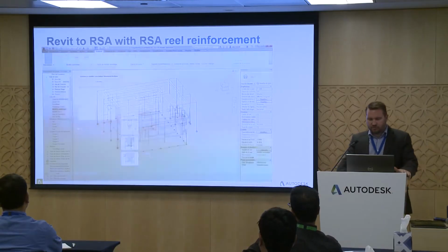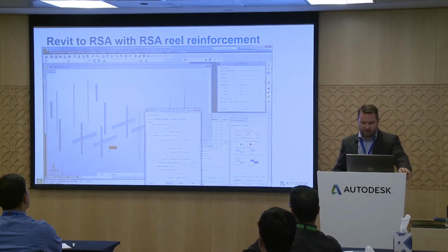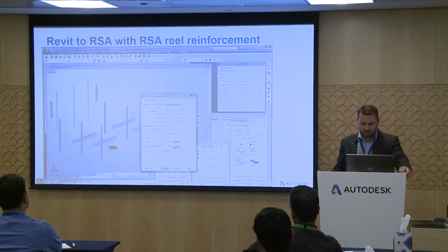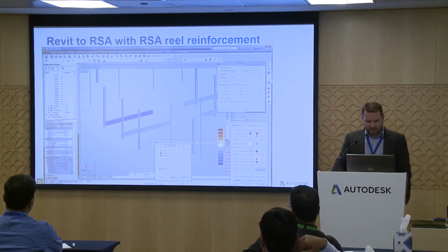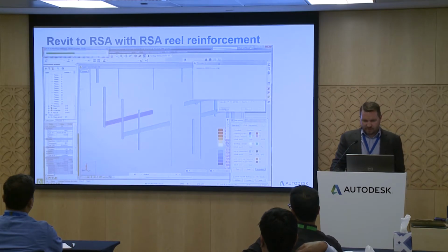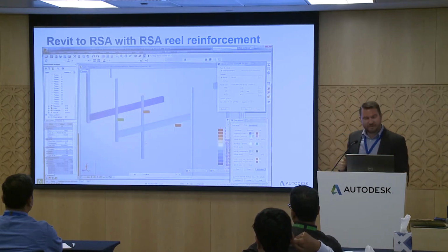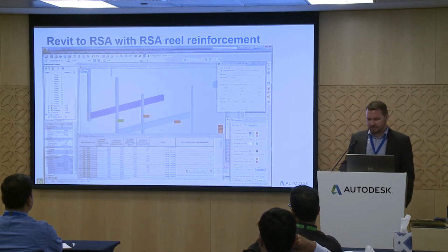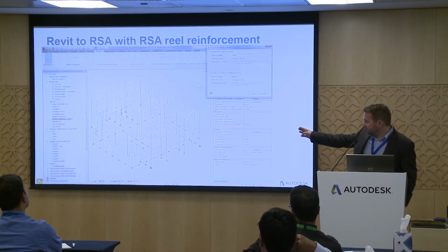So maybe some of you have already known this, but just for you to see where are the elements, here I do the calculation of theoretical reinforcement according to Eurocode with British Standard annexes. So it's Eurocode 2 plus BS. And so I have my result. So I save. Don't forget to save, because sometimes you want to do a fast video and you don't save and say, I have no result. But you have colleagues who say, did you save? I say no. And after you just update.